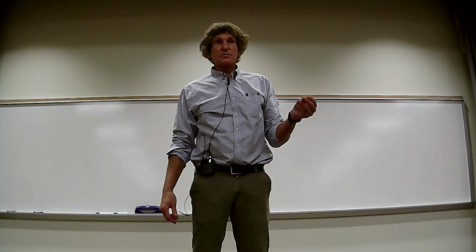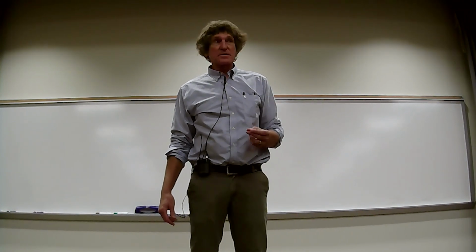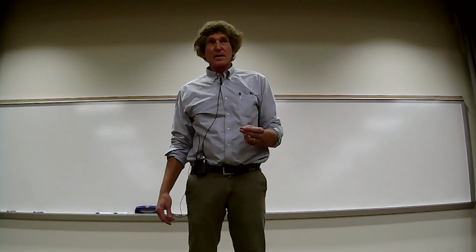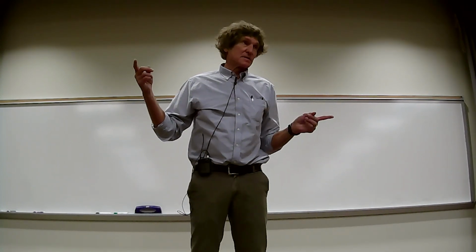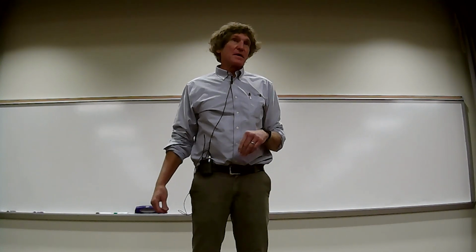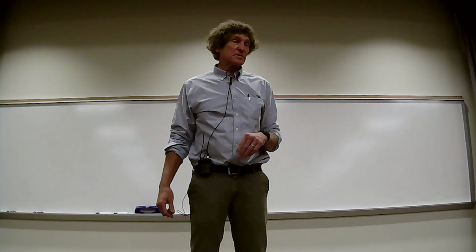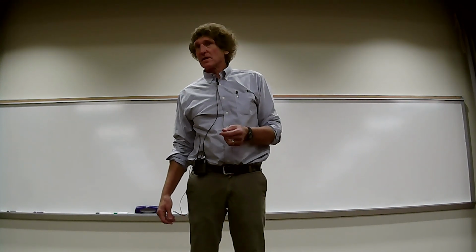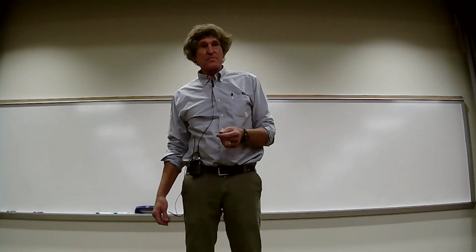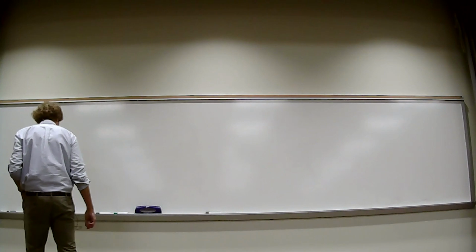For resistance, you assume current usually. Calculate J, the current density. Calculate the E field, integrate the E field over whatever the length is of the resistive ends. And then you simply take V divided by I to calculate the resistance. Now, are there any questions related to this? Anything else? Yes? Could you go through 3.75 and how to work that one out?